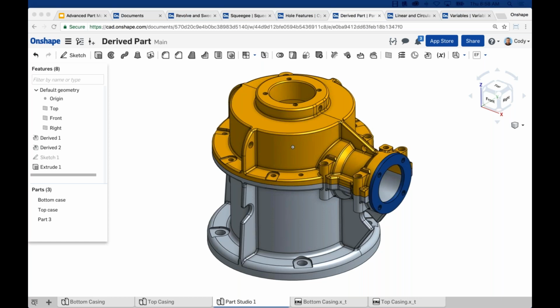In fact, I just recently did a top-down design webinar that walked through the workflow of positioning parts in the Part Studio. I'd recommend transform with mate connectors, or you can go into in-context assembly design.